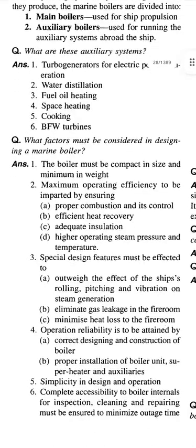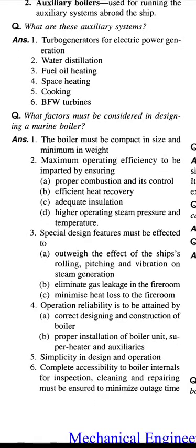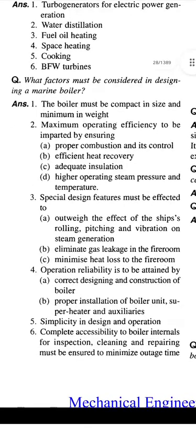What are the factors that must be considered in designing a marine boiler? Answer: first, the boiler must be compact in size and minimum in weight. Second, maximum operating efficiency to be imparted by ensuring proper combustion and its control, efficient heat recovery, adequate insulation, and higher operating steam pressure and temperature.